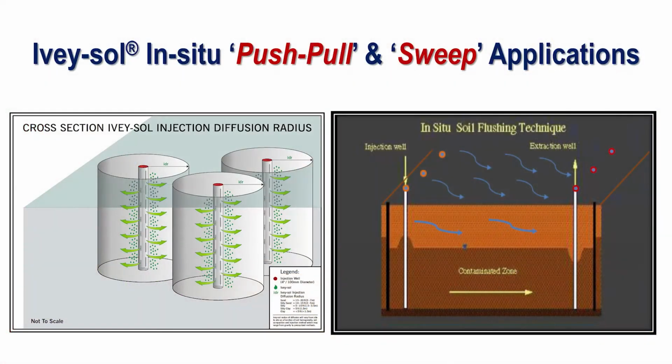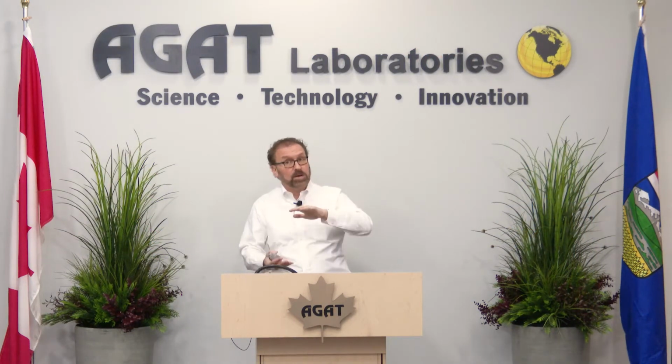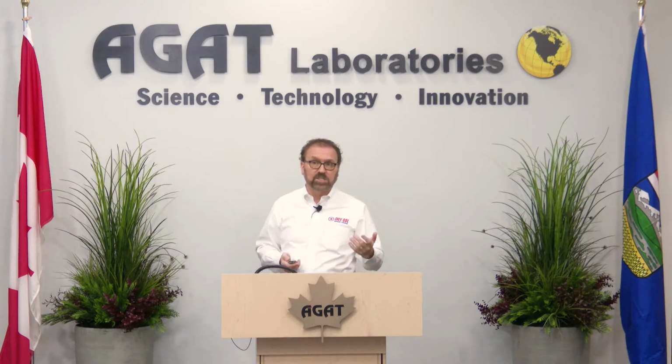So when we're talking about applications, the two most common things that we do is what we refer to as a push-pull. We put in vertical wells inside that area of your plume. They're screened across your zone of contamination. And when your water table goes up and down, by the way, if there's any free phase, it's going to make a smearing of contamination. So make sure you cover that in your investigations to determine it.